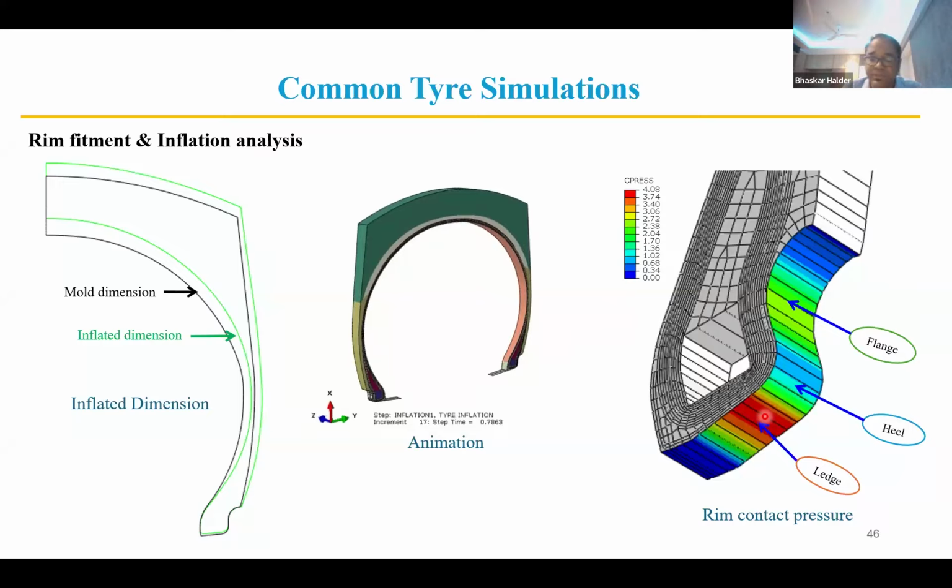Another thing is that there is a flange area. If you see the rim, that is called the flange. And the tire, while in a loaded condition, deflects and takes the support of the flange. So now the question is how much pressure or how much stress I can allow. In that way, FEA gives us some values, that this may be 2.3 megapascal and so on.